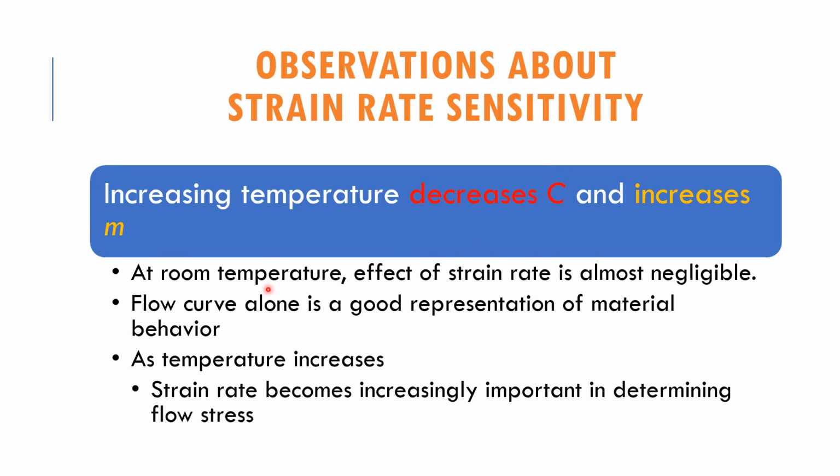At room temperature, the effect of strain rate is almost negligible. So you don't have to consider the strain rate at room temperature, meaning in cold working, it is almost negligible. The flow curve alone is a good representation of the material behavior. When the temperature increases, strain rate becomes increasingly important in determining the flow stress.